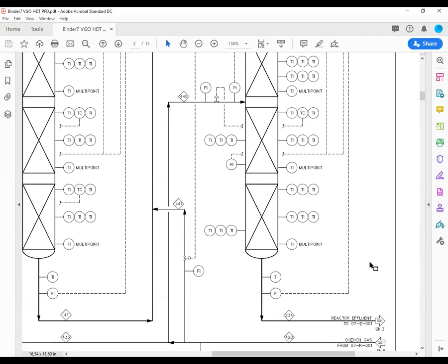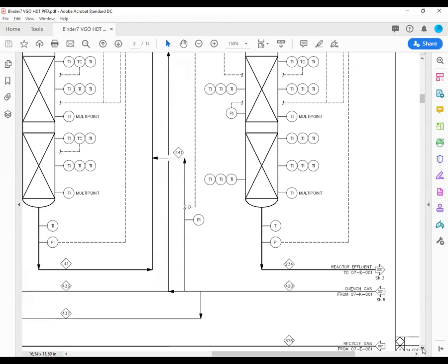We have seen also that we are working with 3 beds in each reactor, for the reason that we have explained. We have a lot of H2S formation, because we have a quite high amount of sulfur in the feed. That's why we have to be very careful with the recycled gas purity to get an appropriate activity of the catalyst. So that's everything I had for today, but if you have questions, please.